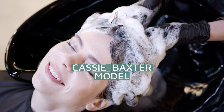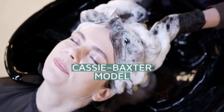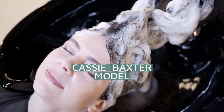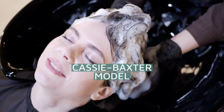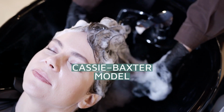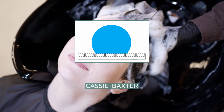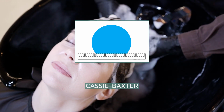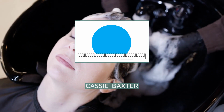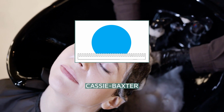Cassie-Baxter model. When dealing with a heterogeneous surface, the Wenzel model is not sufficient. A more complex model is needed to measure how the apparent contact angle changes when various materials are involved. This heterogeneous surface, like that seen in Figure 8, is explained using the Cassie-Baxter equation, Cassie's law. Cos theta asterisk equals r_f f cos theta_Y plus f minus 1. Here r_f is the roughness ratio of the wet surface area and f is the fraction of solid surface area wet by the liquid.